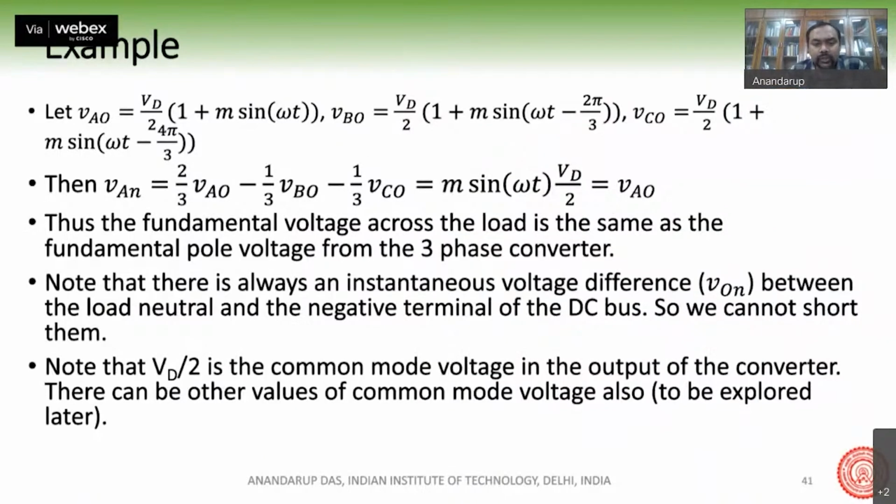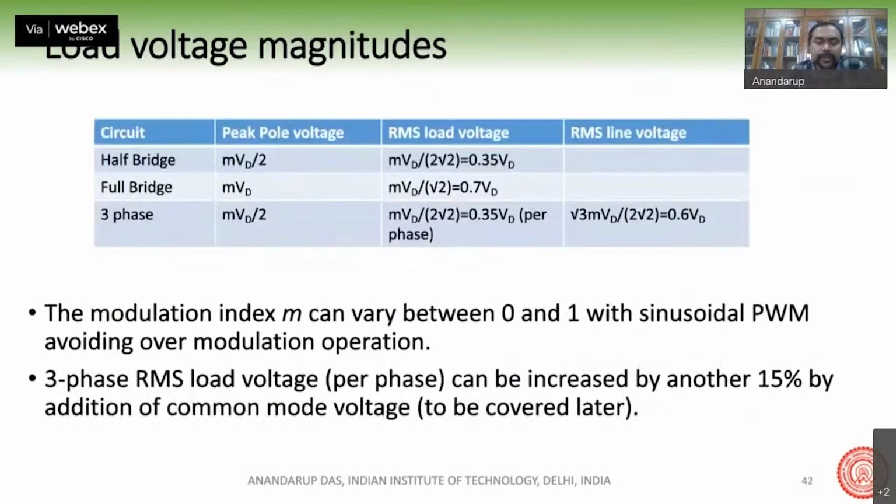This common mode can be extended for getting the space vector also when we do space vector PWM. And these are some of the load voltage magnitude expressions. These you can find out yourself. And you can see the difference between half bridge, full bridge, and three phase, and how much voltage is possible from the converter.